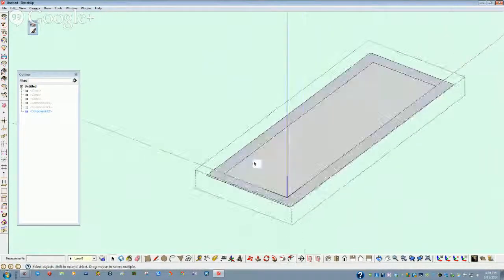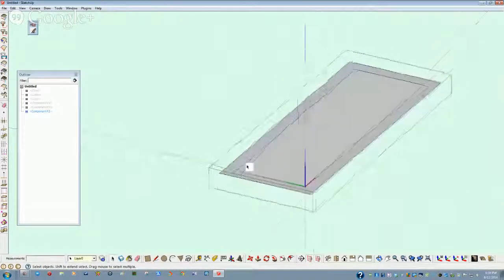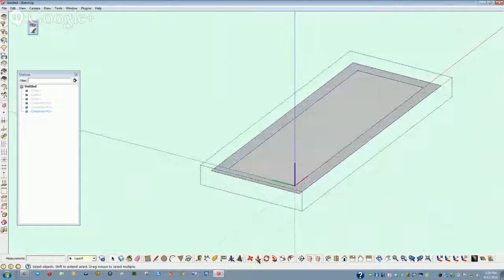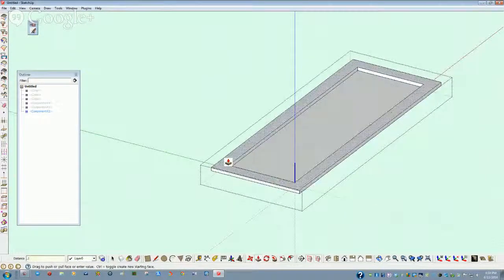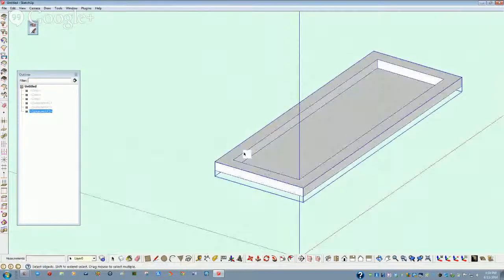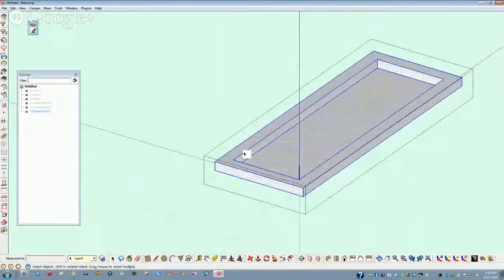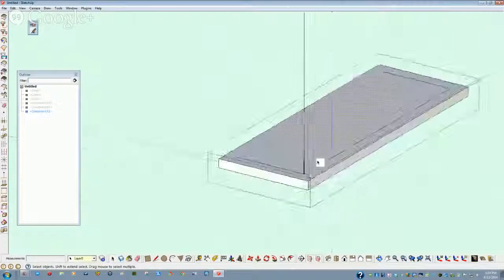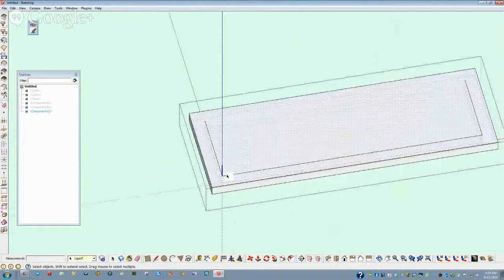Now, unfortunately, it doesn't like what I just did, but the fix is easy. I'm going to take this up and put up 3/8 of an inch. By removing that one line element, I made that top a complete solid feature.